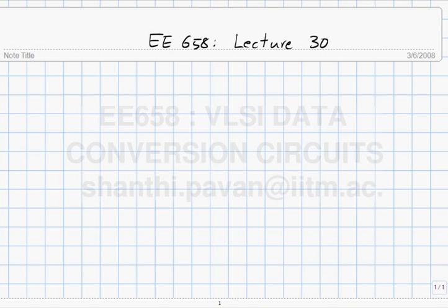And a quantizer is something with an analog input and an analog output. You want analog to analog, but you can think of it as doing this in two steps. One is analog to digital, and then you need something to convert back to analog. So this is an A to D and a D to A converter in cascade. So we'll spend some time looking at D to A converters and understanding what these things do, so that we can put these two together, the flash A to D converter and the DAC, and make a quantizer.